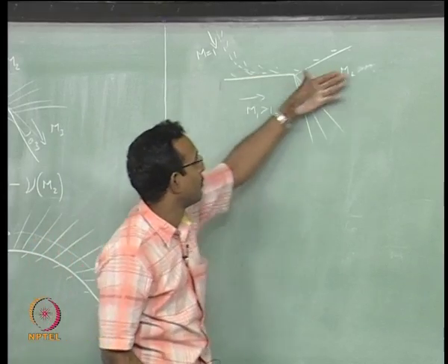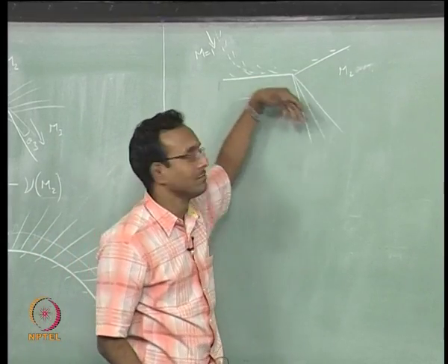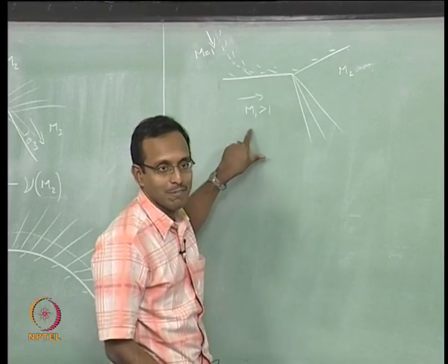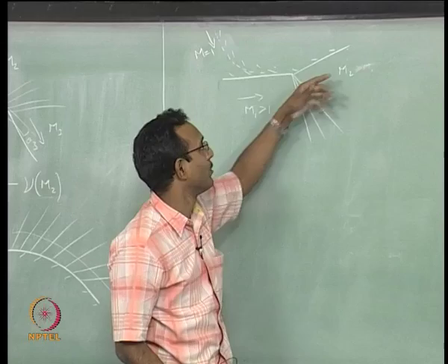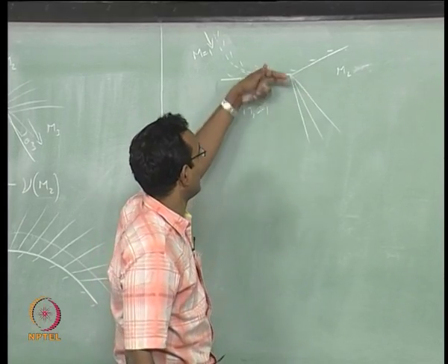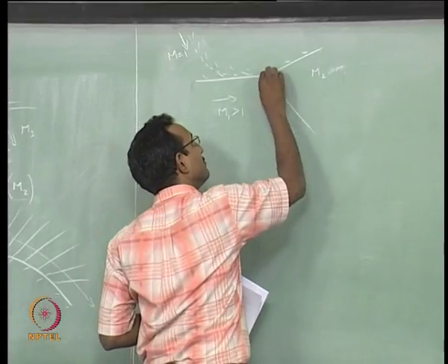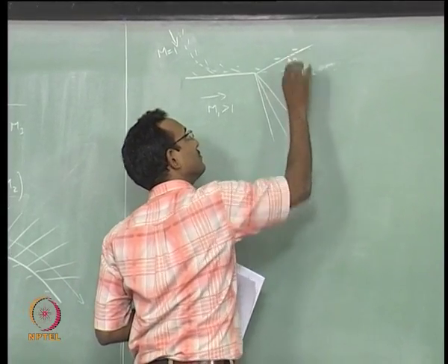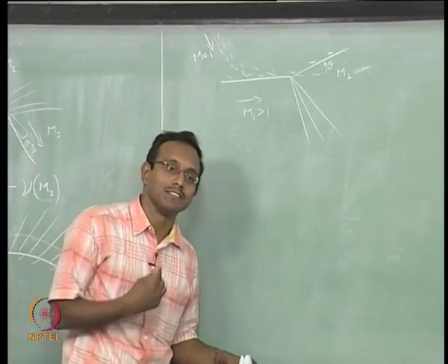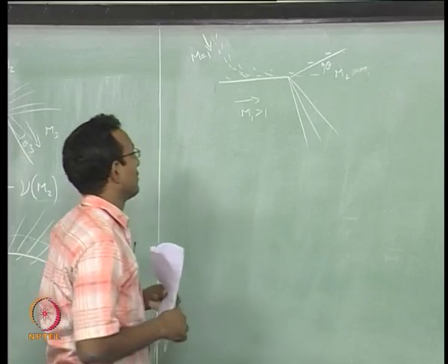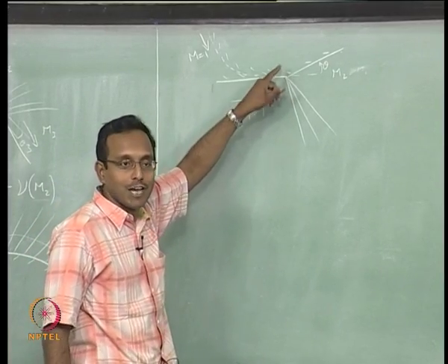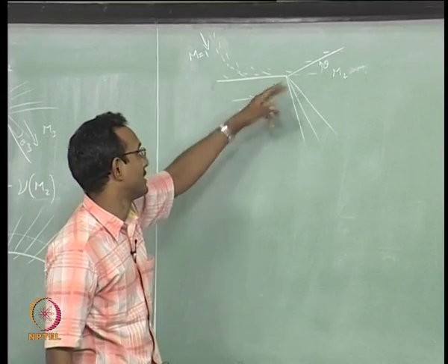And then if I expand more, it may go to 3. The total expansion from the M equal to 1 direction to here, the difference in nu, will be equal to that total deflection. This will help you understand the problem, so you will never make mistakes in this case. And of course you can always make it a smooth corner or a sharp corner depending on the problem, it should not change anything.